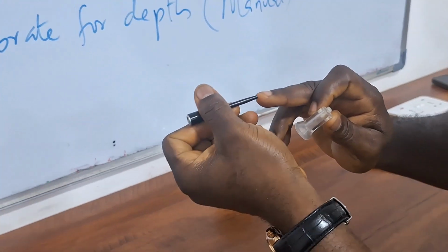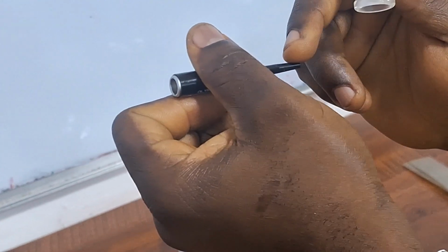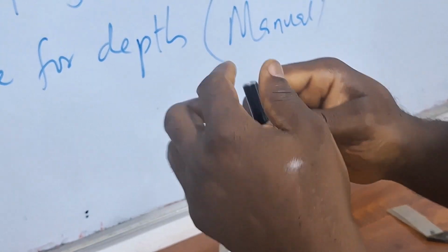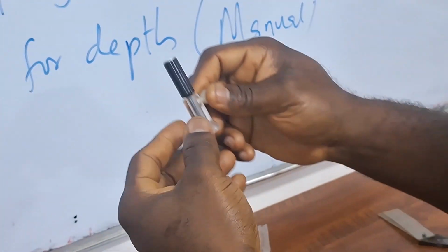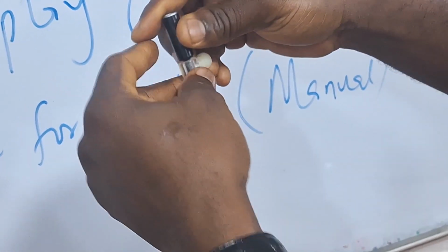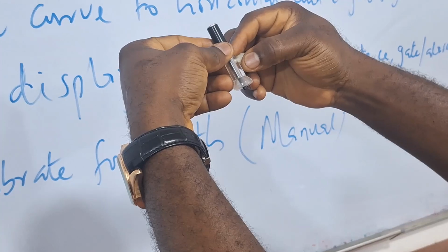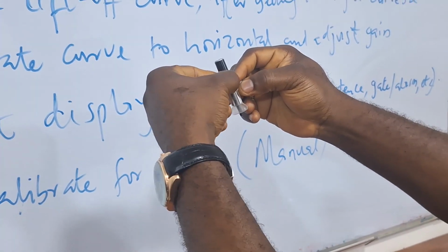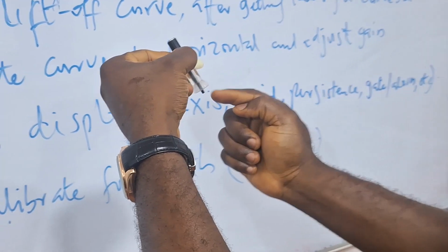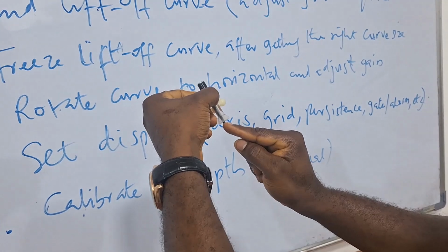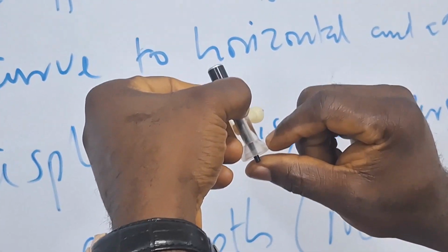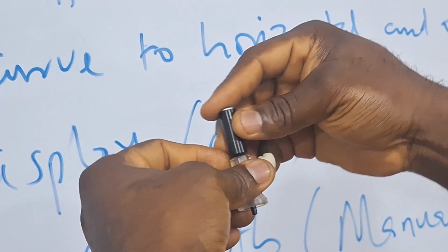But this time, instead of having the coil on the surface, the coil is at the edges here so that it can make contact with the hole. This is a kind of fixture so that you can bring it up or down. The distance between this edge and the tip will be the depth of the hole that you can inspect.